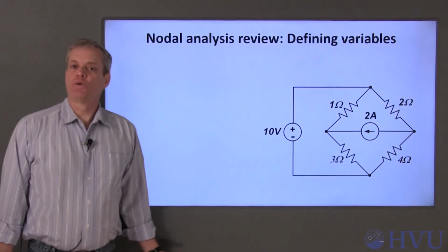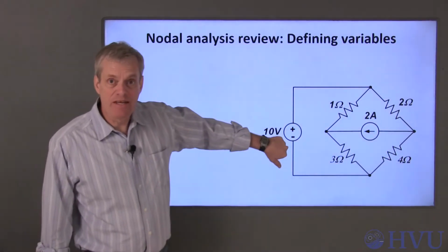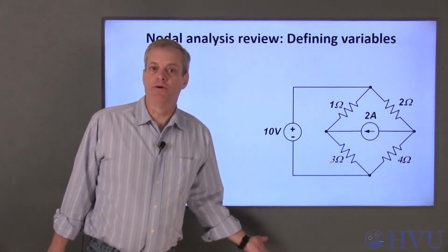Once you've chosen reference, independent, and dependent nodes, the next step in nodal analysis is to perform KCL at the independent nodes. The trick with nodal analysis is that Ohm's law is used to write KCL in terms of the node voltages. I'll develop nodal analysis in terms of the same example I used in the last video.